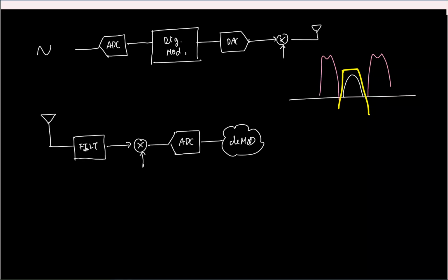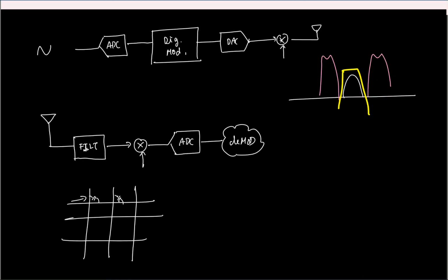And not just that, when you have your touchscreen, your touchscreens are all capacitive touch, right? And again, loosely speaking, it's like a crossbar structure like this. And the idea is, whenever you make a touch, the capacitance around that location is going to change, right? Because the plates are going to move, and the change in the capacitance is what is sensed to detect if the touch is made or not. And how much the capacitance changes determines the sensitivity of the touch, right? You have this pressure sensitivity nowadays.